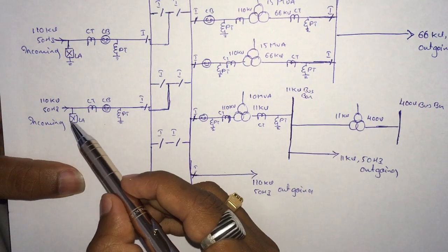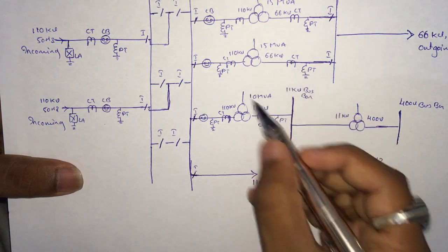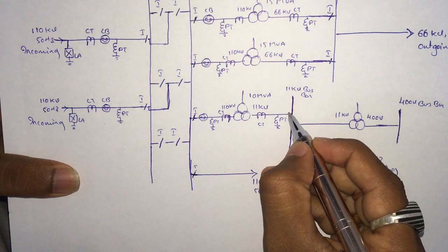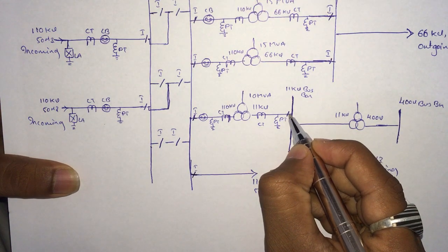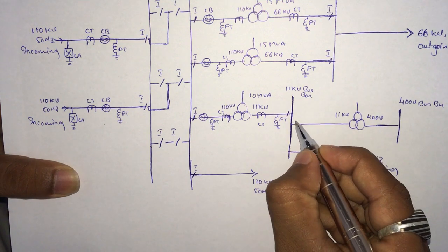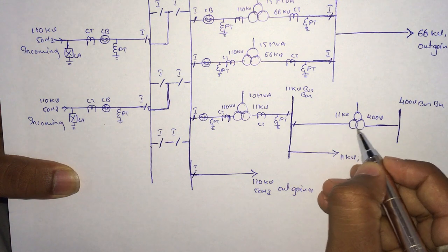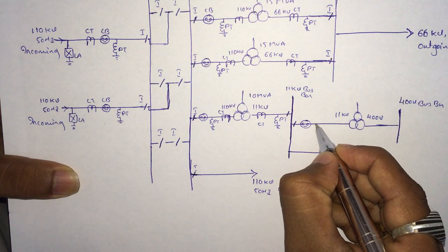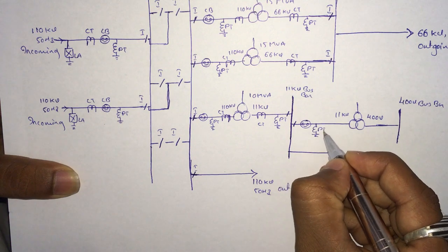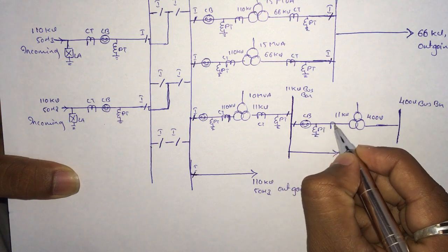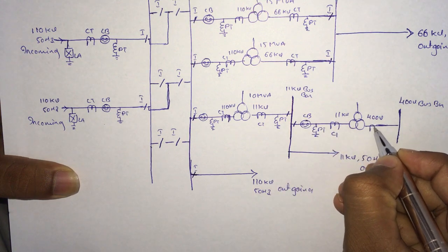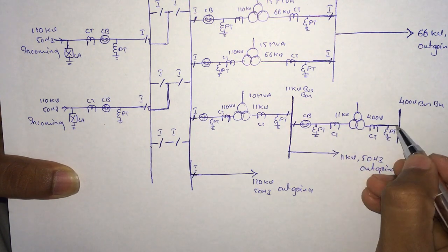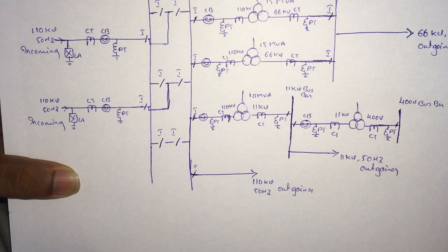You can see the potential transformers are always grounded, similar to our lightning arrestor. Okay, and we got one more transformer here. Sorry, here we left an isolator before the bus bar, isolator, and again after the bus bar one isolator. Now we got the transformer. Before the transformer, for this line we are having one CB, PT, here it is CB, PT, and CT. Again here also CT, PT. PT is always grounded. Before the bus bar, one isolator.